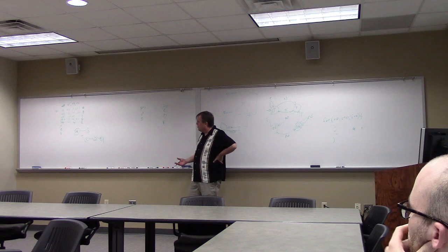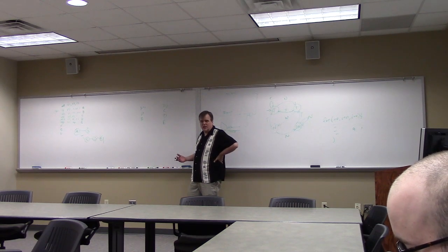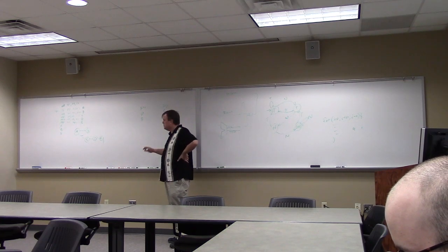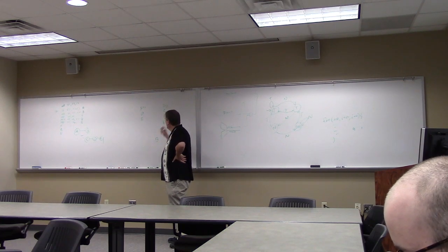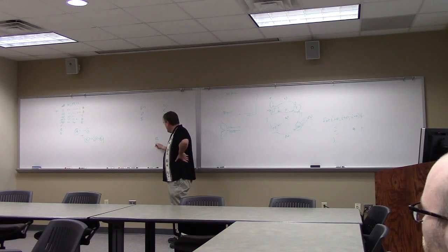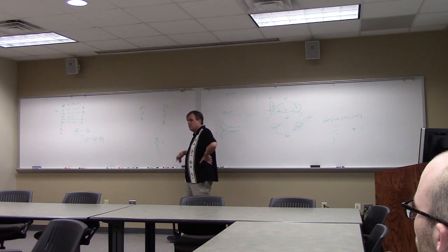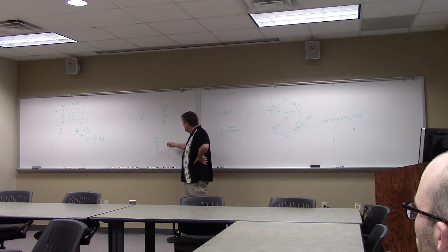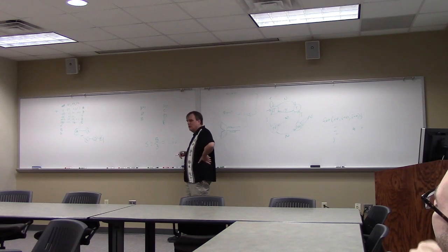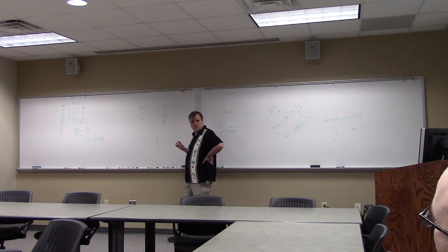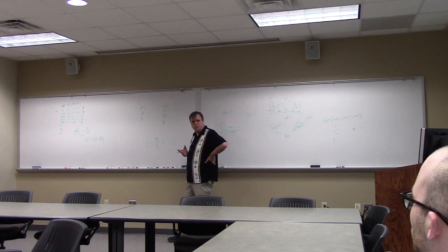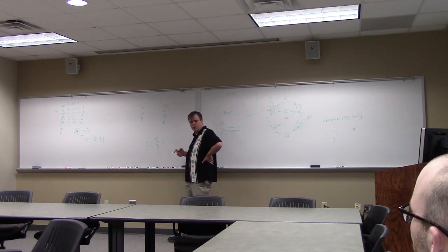Before, it was taking me 5 or maybe 6 cycles to complete a loop. Once I had the really efficient packed version, it was 5 cycles. Now how long does it take me? 3 cycles. So if you look at that, my speed up is 67% basically. It's a pretty good speed up. It's not the 100% speed up I'd love from a dual pipeline system, but it's still pretty good.